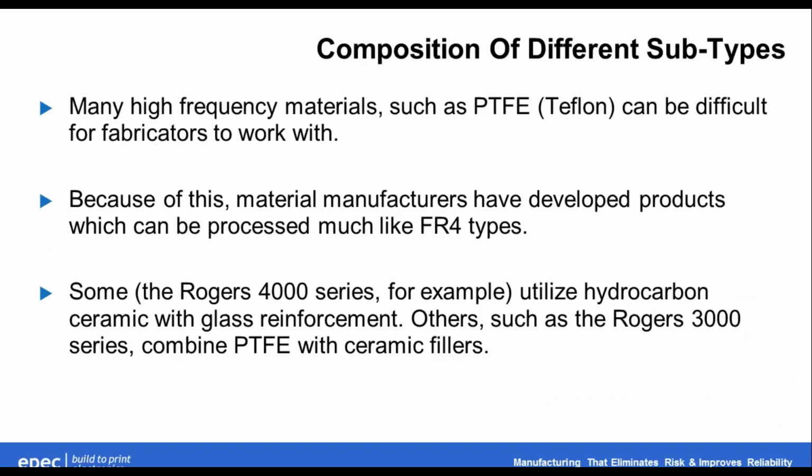Now, different subtypes of this high-frequency material have different compositions. Many high-frequency materials, such as PTFE, which is Teflon, can be difficult for fabricators to work with. Because of this, the material manufacturers have developed products which can be processed much more like FR4 types, and that helps the fabricators to stick more with their normal process sequences.